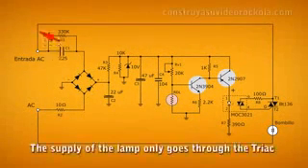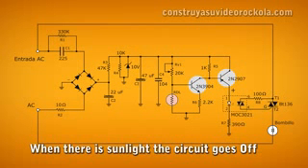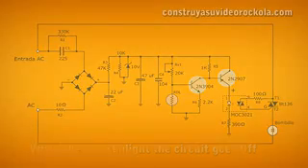When the LDR returns to receive light, its impedance is low and it negatively biases the 2N3904 transistor base. Since the transistor is NPN, it becomes non-conductive, and therefore so is the other transistor. The optocoupler and triac no longer conduct, and logically turn off the bulb.